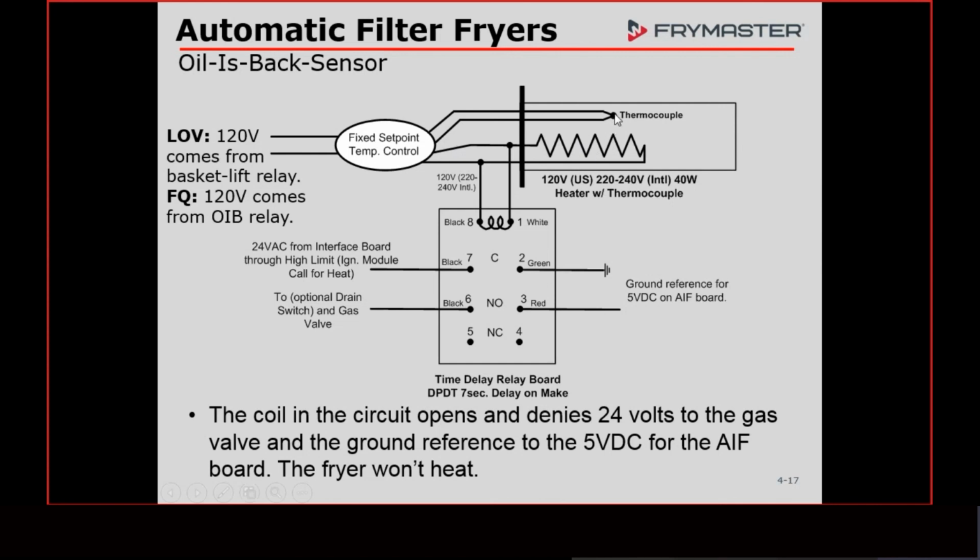So once this heater goes off, or once that thermocouple sends a signal back here to shut the heater off, the 120 volt goes away. All right? It's going to go away until the thermocouple sends another signal back saying, we just dropped in temperature. We're below the 550. We need to come back on. That happens in about 3 seconds, okay? So that takes about 3 seconds.